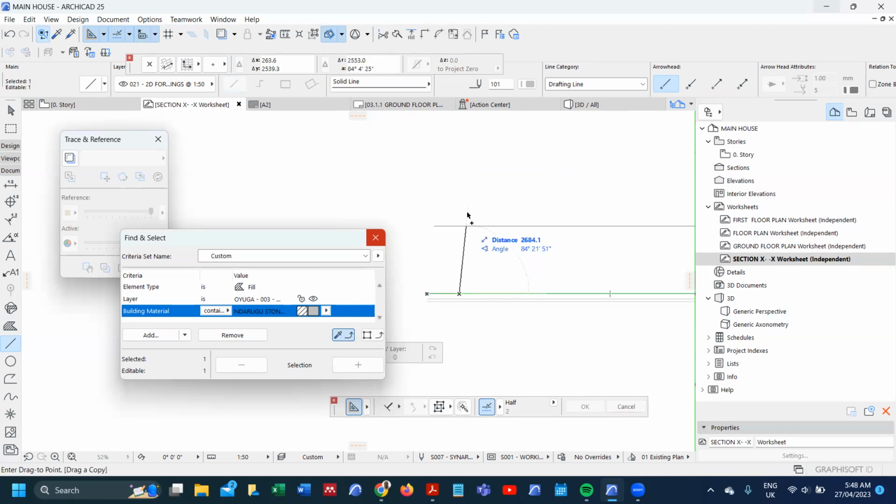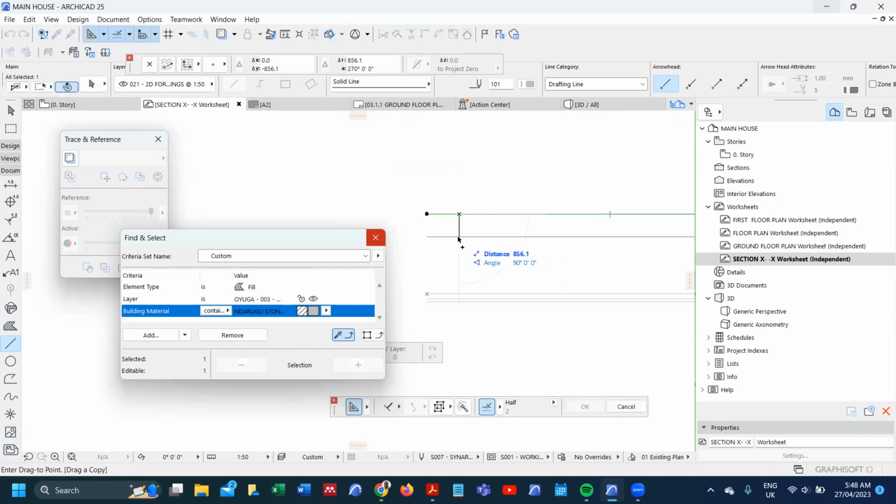Then our first floor is 3 meters. But since he has used hollow pot, most probably we'll have a depth of around 300, okay, as opposed to 150. And then our beams will be 600.